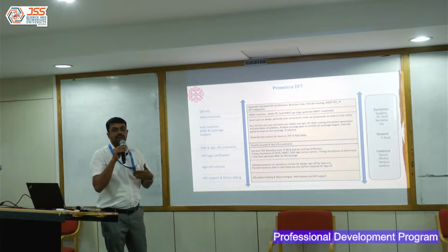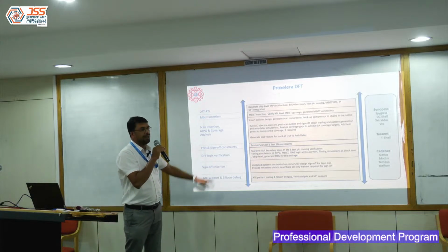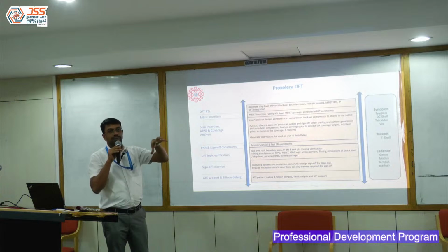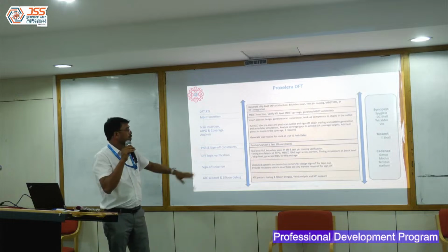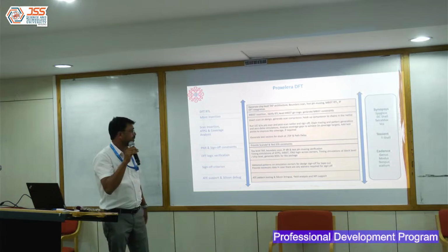Simulation is something like a design verification. Whatever you have done, how do you verify? You simulate it. So we do a round of simulation. We do coverage analysis. Coverage analysis is like, am I covering the complete logic in the design? Am I covering all the nodes in the design? Typically we have a requirement that the coverage has to be 99%.